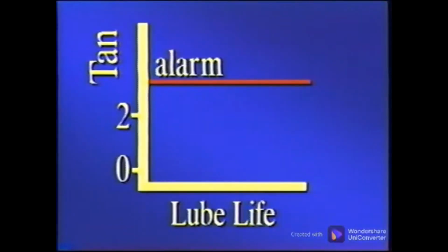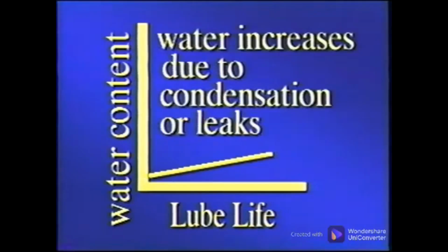The TAN of a new lubricant should be 0.0 to 2.0. An increase in acidity by 2 points or 50% indicates there is a real problem with acidity. Water content in a lubricant should be low when the lubricant is new and goes higher over time due to condensation or leaks in the system.